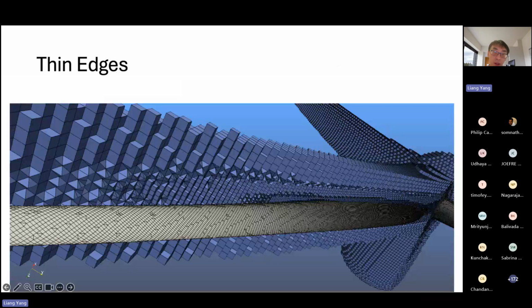Another thing I would say is a bit challenging for this type of volume to surface mesh is capturing the trailing edge parts of the geometry. I'm not sure if you have tried these geometries in snappyHexMesh; probably you get some very strange shapes, because the trailing edge is very hard to capture by the traditional volume to surface approach.